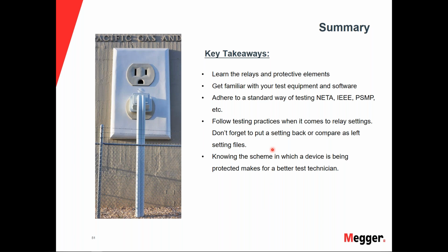Follow the testing practices when it comes to relay settings. Pull them before you get to the relays. If you have electromechanical relays, we all have phones. Take a picture, write it down, whatever it takes for you to remember what the settings are, before you touch the relay. So if you have to take a picture of it, if you have to write it down before you pull it out of the panel, great.